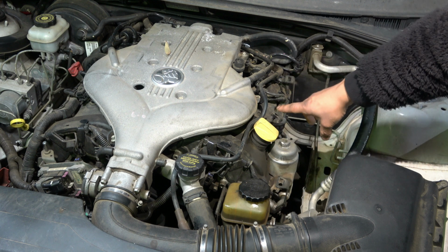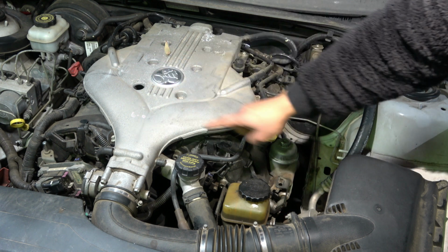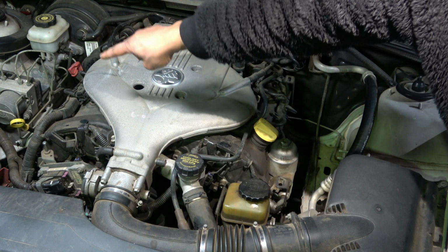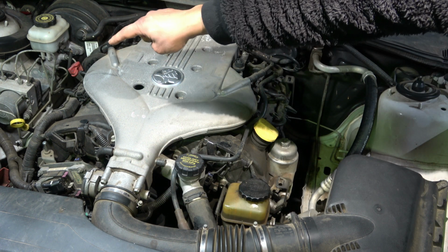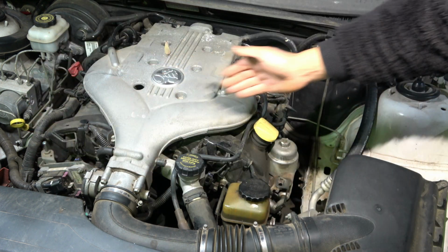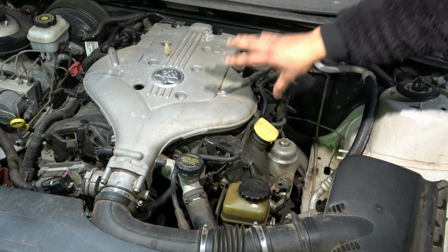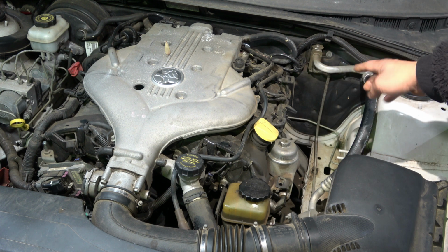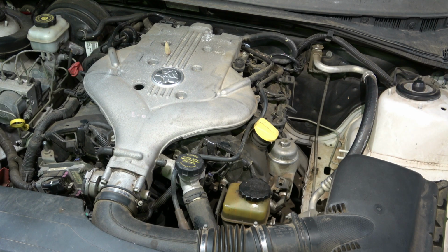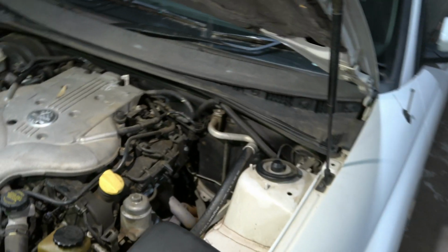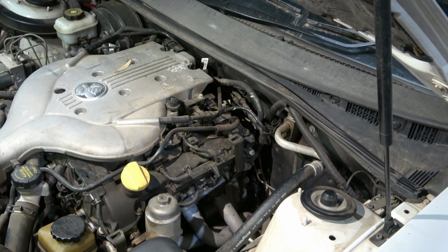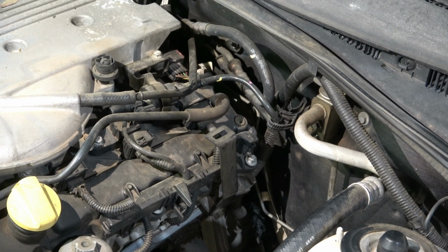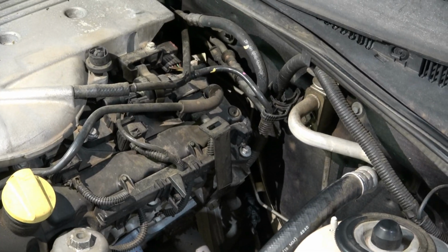Also, another way you can tell is the coil, the first coil on each bank, which coil is towards the front. In this case, that coil on bank 1 is sticking out further that way compared to this one. So this is bank 2, and sensor 1 is a pre-cat sensor, which lives down here before the catalytic converter. That's the fault. So we're going to do some testing there. I'll just focus you down there. So it lives down there. I don't know if you can see or not, but I'll try my best. Down there somewhere.